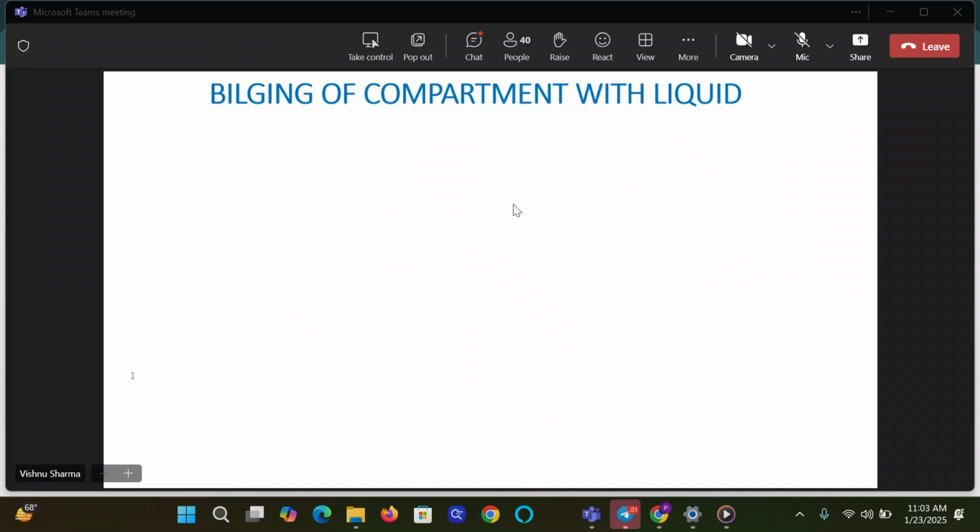of your tanks, what do you get to hear, guys? You get to hear the tank breathing heavily, air gushing out and gushing in as the liquid moves from side to side. Yes or no, beta? Have you heard that in rough weather, if you go past the vents of tanks carrying liquid? Yes, sir. You hear that air going in and out heavily, the tanks breathing heavily. Here the liquid could not escape because the hull is intact. So the air was escaping and coming in and going out.